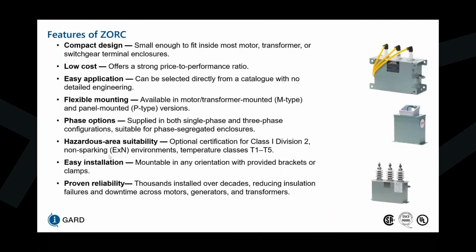We also have hazardous area suitability, so optional certification for Class 1 Div 2, non-sparking environments, and temperature classes T1 to T5. Very easy to install, so it's mountable in any orientation with provided brackets or clamps. And it's proven to be reliable because we have thousands installed over decades, reducing installation failures and downtime across motors, generators, and transformers.